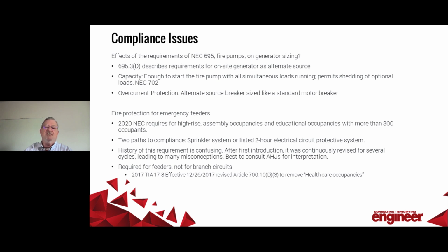NFPA 110 says that an energy converter has to have capacity to start and carry its loads according to its EPSS type. That means that it has to be stout enough to add the fire pump to its maximum load, or it has to have load shed to drop lower priority loads in favor of the fire pump. Now, the NEC covers fire pumps in Article 695 and makes that same statement explicitly in 695.3(D). There's a popular misconception about NEC requirements for standby service to fire pumps.